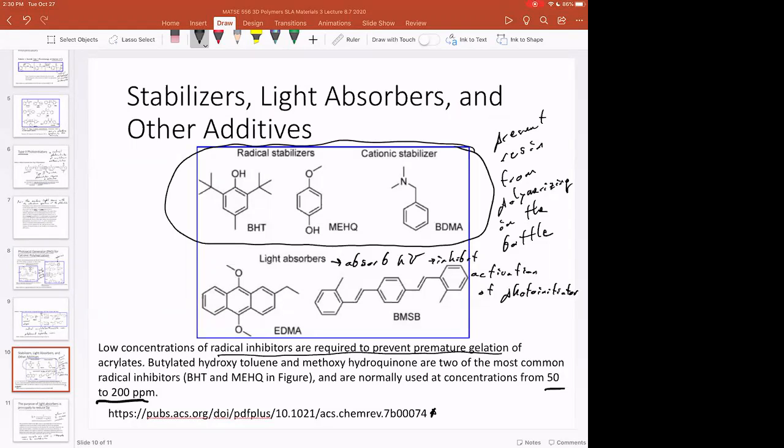These liquid resins are much more hazardous because they're reactive chemicals, and everything is stuck in there after you make the part. Even when you wash it, you're just washing off a lot of the surface layers. You're not really getting in there and extracting all of these different reactive species from your SLA part. And so this is why SLA resins have to be handled with more care, and it's less common to be using these outside of a controlled environment. That's something to remember when you encounter stereolithography resins. It's just not the same as reels of PLA or ABS.